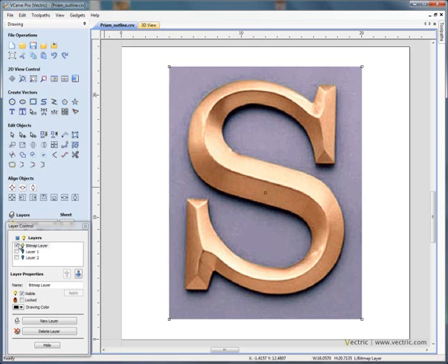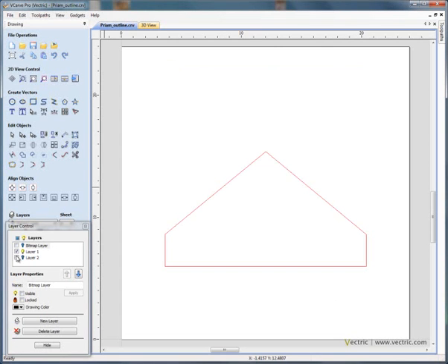If we just delete this for a moment, or switch the bitmap layer off and show a schematic, this is a cross section through one of the letters, and the software calculates the toolpath to use a wide angled V-bit. Here we've got a 90-degree angle V-bit to form the edge on the lettering. So the software calculates toolpaths that will plunge into the material and form this edge at different depths. So the tool will move down, forming the edge of the lettering at each pass.